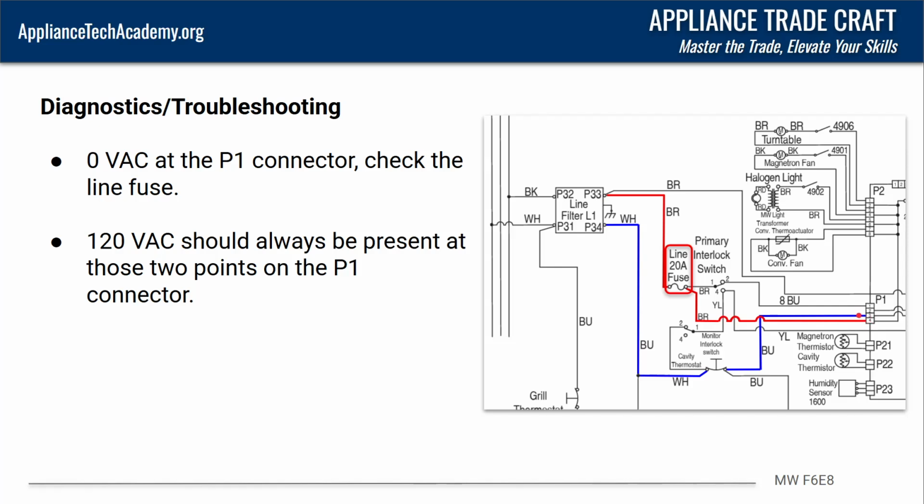But on this line, this is how the control board gets its neutral. Again, circling through here, neutral comes up through there. So when you have line voltage on one side of a load and neutral on the other, that load should work. When you are missing either line or neutral, that load becomes a conductor. It just allows voltage to pass right through it, so it kind of backfeeds through.